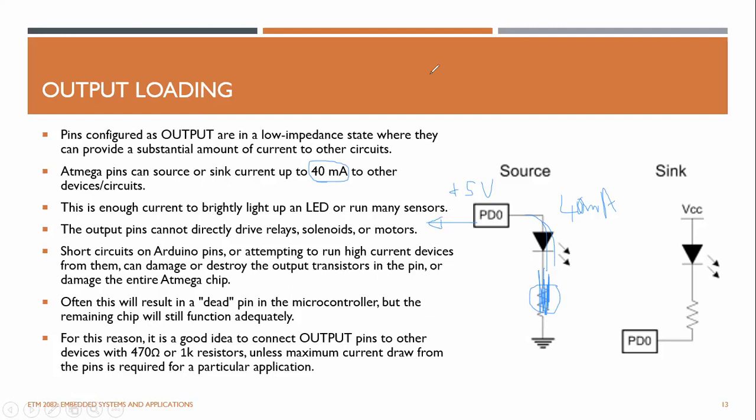Or sometimes if you short circuit this pin to the ground somehow, like with a piece of wire, when it is 5 volt, you are literally short circuiting the port to the ground, right? Accidentally, if you do this also, the particular pin will be damaged.